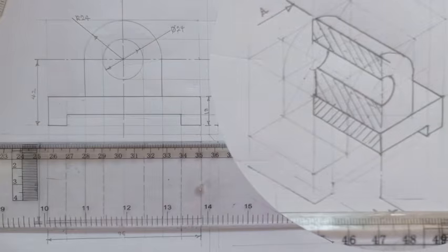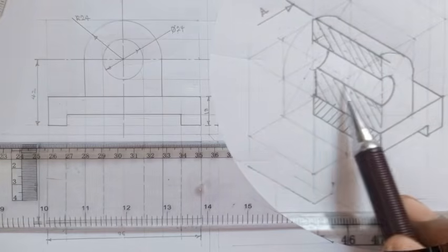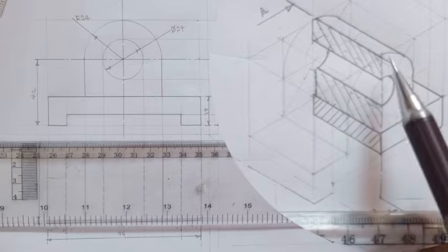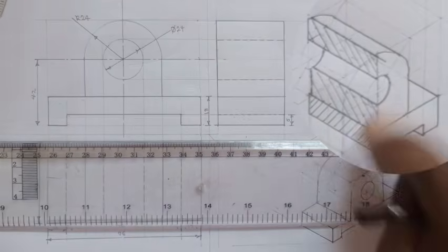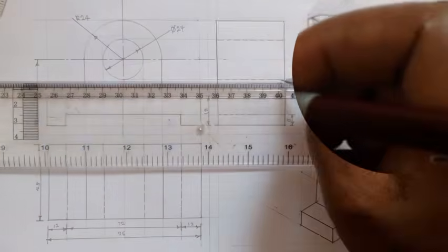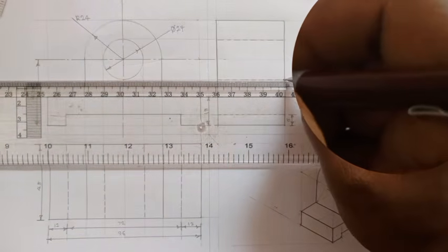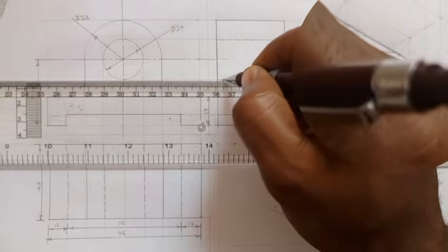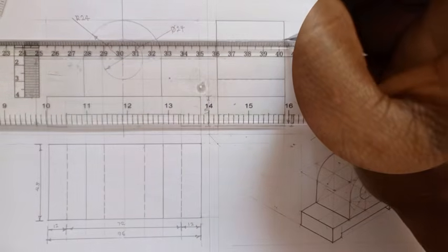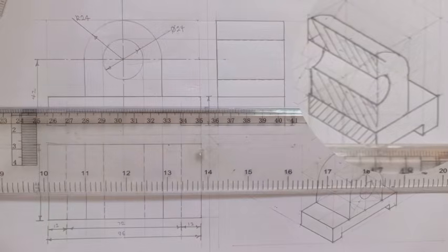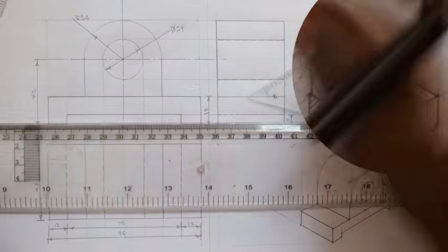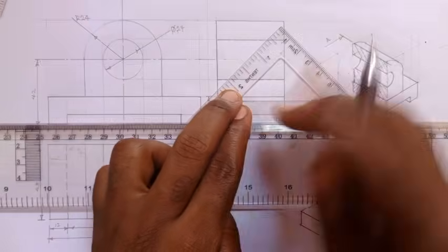Now since we've done that, you see that there's still a hole, so all the hidden line will become what? Thick line. Then you section. So I want to implement this here now. So this line, instead of writing my hidden line, I'm going to draw this way. And I'm going to draw this way. Then I will now section it using my 45-degree set square. Section those two parts to expose the hole.